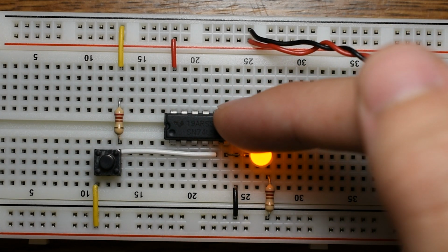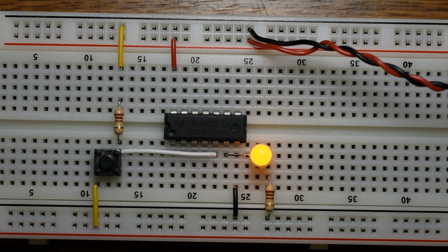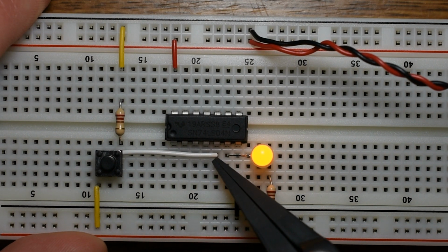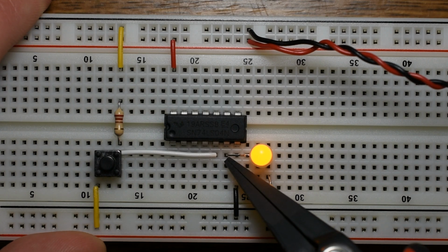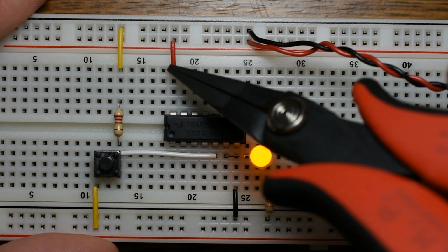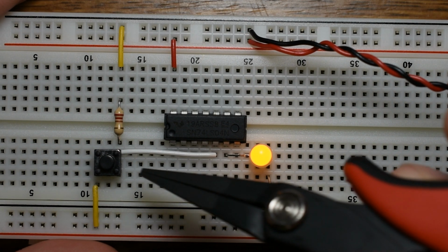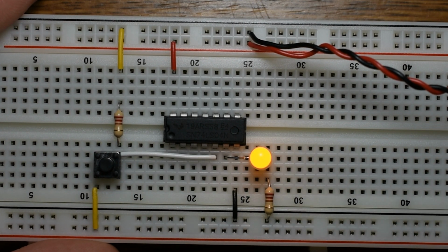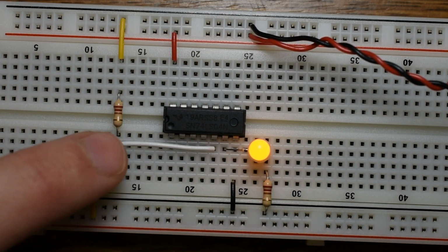This chip is called the 74LS04, and it has 6 inverters inside of it. The only pins I'm using on this chip are this input where the white wire ends and this output where the LED is. Those are the only 2 pins I'm using, except for, of course, providing power to the chip. And other than that, all I have is the input circuitry with the button and the output, so we can see it with the LED. And it works just as expected.